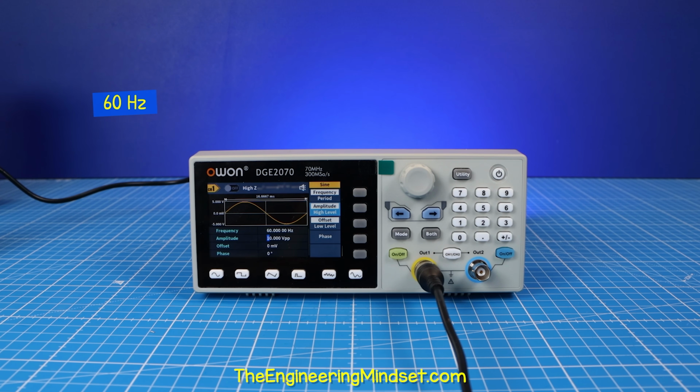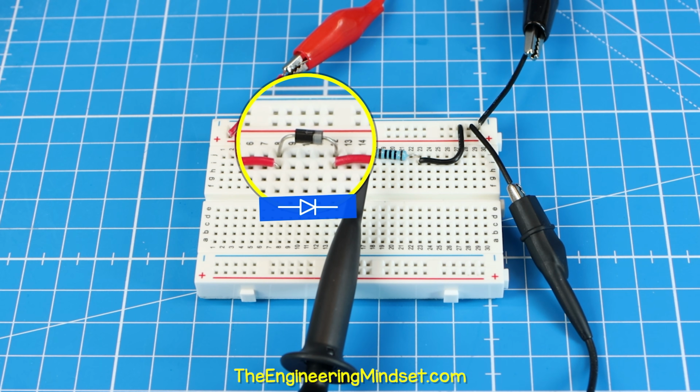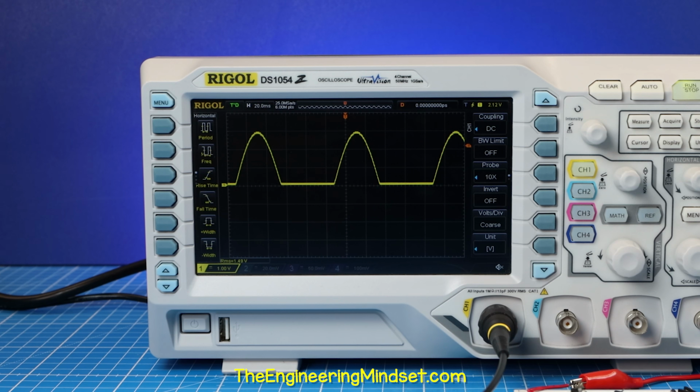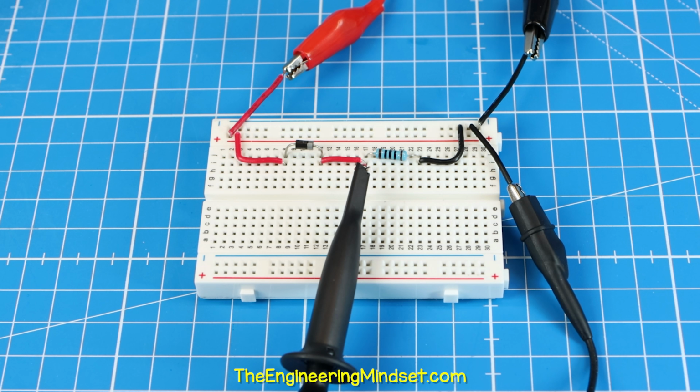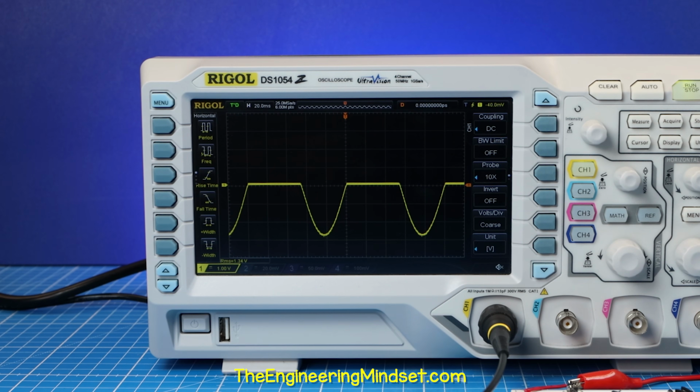Using a 60 Hz 10 volt peak-to-peak sine wave, if we insert a diode into the circuit like this, it will block the negative half of the cycle. If we reverse it, it will block the positive half.